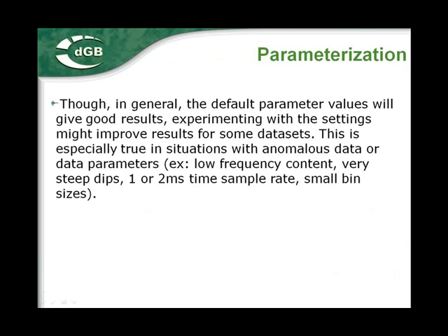Some thoughts on the parameterization. The default parameterization in the previous examples is usually pretty good, so usually you can go ahead, but you shouldn't stop thinking. First of all, after creating the steering cube you should always display it on a section view in a semi-transparent way, to check if it's not noisy and if the values are accurate.